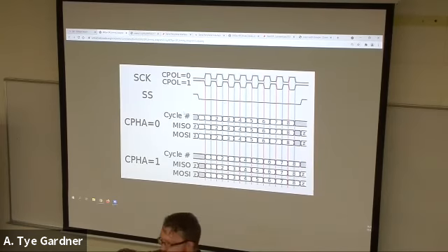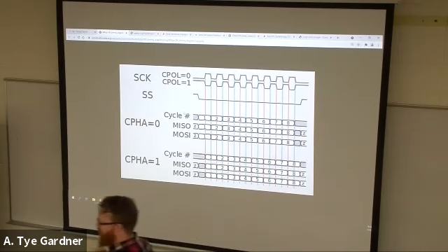Very clearly labeled on the bottom 2 pins of this, if I'm oriented this way, is ground and then 3.3 volts. If you're using a multimeter to measure voltages, be very, very careful to not short those 2 together because you can break your board. You won't necessarily break your board, but it is likely. It has over voltage protection. It tries to save it, but it won't necessarily be successful.